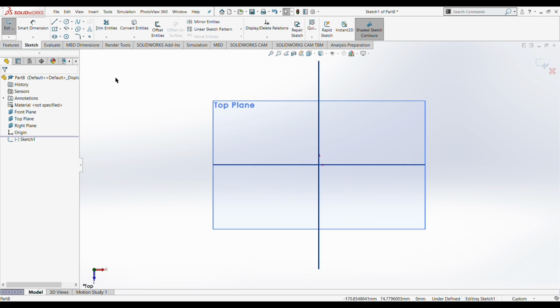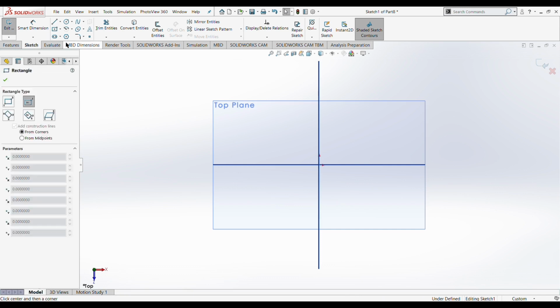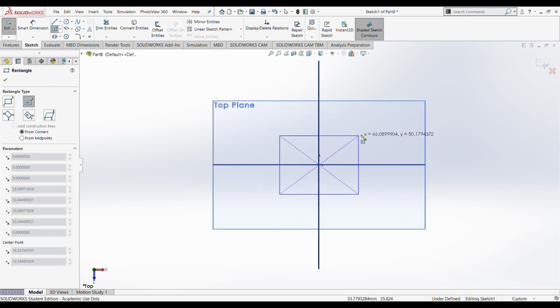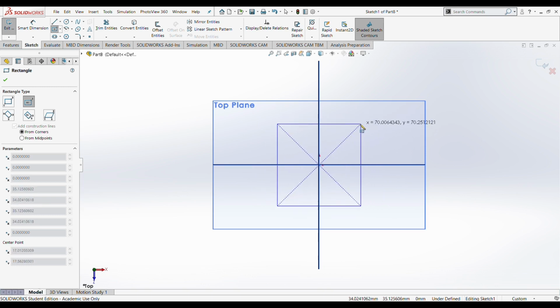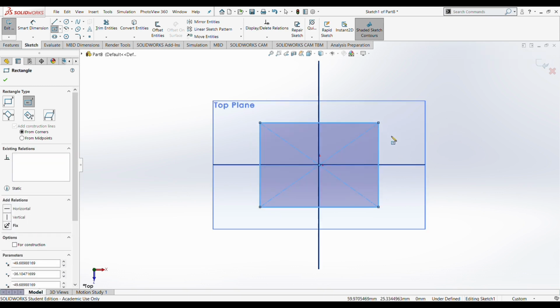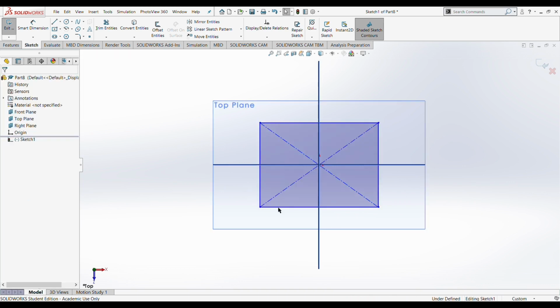The way we do that is that up on the sketch tools, we have a bunch of different options that we can use to create a drawing. We're going to go ahead underneath rectangle, hit the drop down arrow, and choose center rectangle. This will let us draw a square rectangle starting from the center of our planes, or the origin that I mentioned. So if we click over here and drag out, now we can see that we're creating some sort of cube, some sort of square or rectangle. And if we click again, it lets go. Once we hit escape, we have our square, or our rectangle.